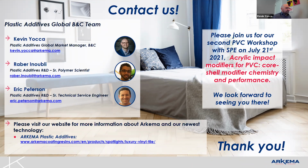And so you can imagine that you've probably passed the optimum of where you want to be for the gelation and processing of that PVC article. So the more you incorporate, the torque may get higher, and the amount of work you have to do to get the final part fused well may change. Typically, we're hoping that your balance of lubricants is keeping things from burning too much with the addition of the regrind, especially if it's beyond like 30% or 50%, and you're managing the torque as well as you can and still getting good mechanical properties on the other side. So yeah, it has a huge effect from that point of view.